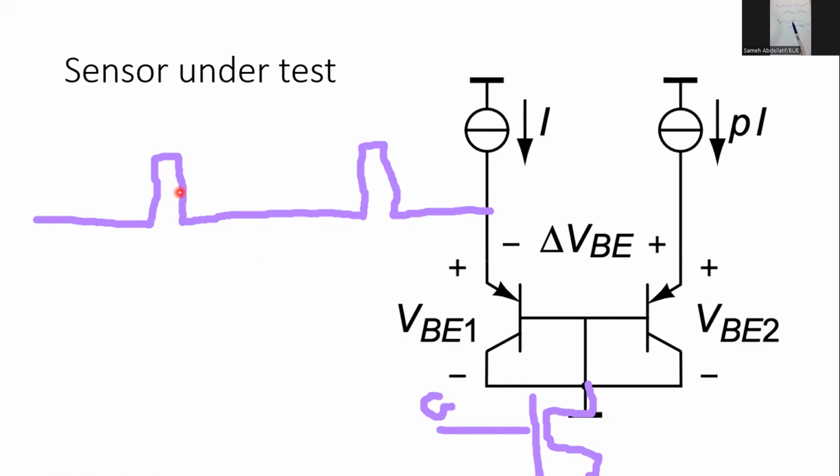So in every 5 minutes, you will only open or turn on your transistor for just milliseconds to sense the physical parameter to be sensed. Otherwise, your sensor is turned off and your energy consumption is minimal.